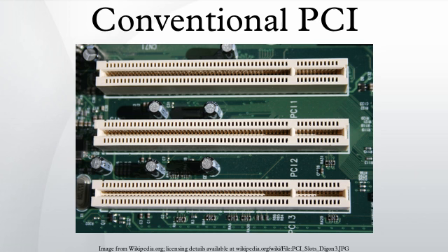64-bit addressing is done using a two-stage address phase. The initiator broadcasts the low 32 address bits, accompanied by a special dual address cycle command code. Devices which do not support 64-bit addressing can simply not respond to that command code. The next cycle, the initiator transmits the high 32 address bits, plus the real command code. The transaction operates identically from that point on.